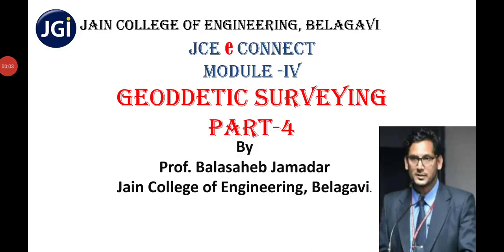So today we are going to study geometric surveying part 4. This is part 4 of geometric surveying, where we are going to study the reduction to the centers, and here we are talking about the satellite station as an eccentric station or arbitrary station, in order to secure a well-conditioned triangle or better visibility.